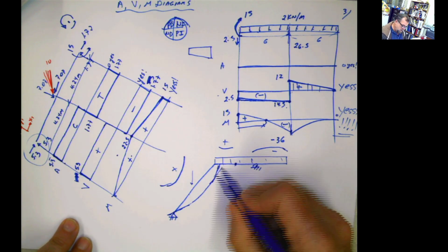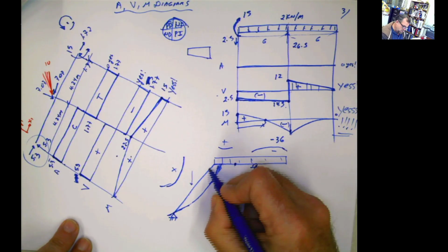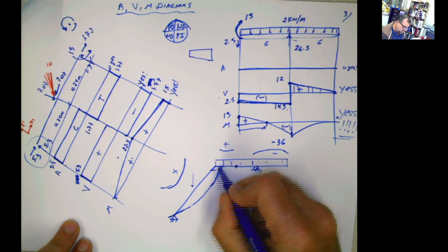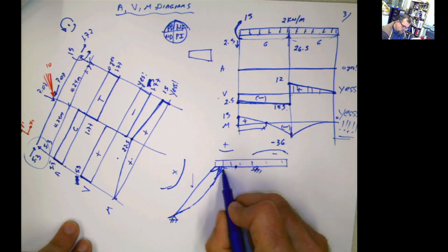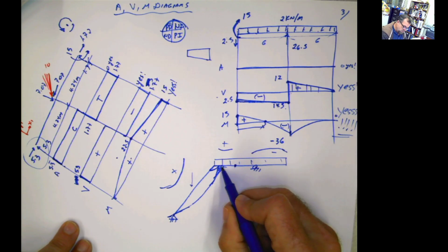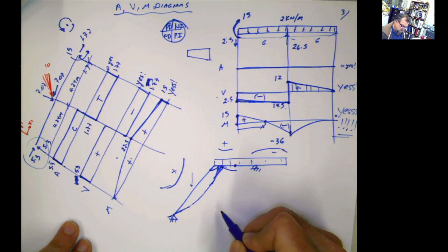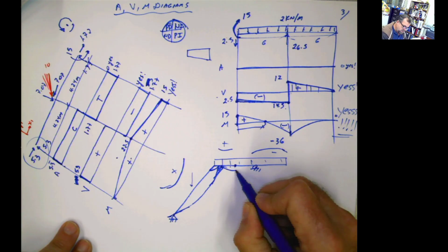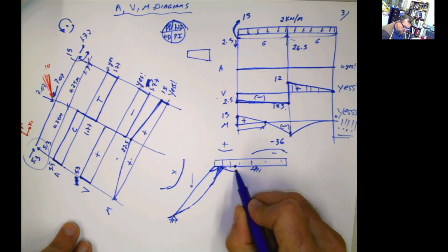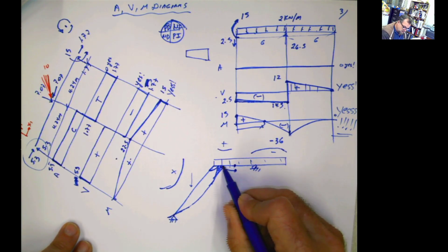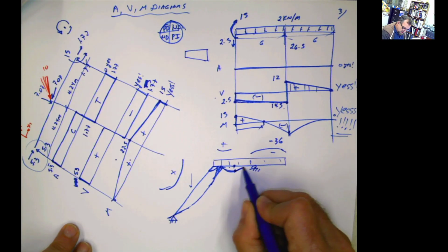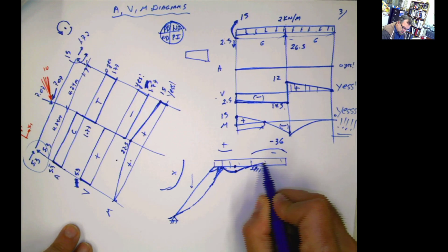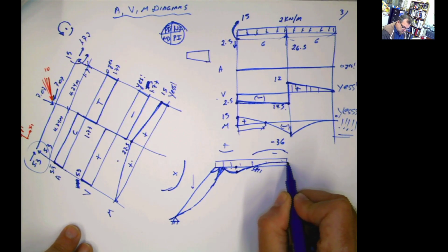But this is a moment connection, so that angle that I have over there has to be maintained somehow here. And this is positive up to this point, like there. And then after that, everything becomes negative. So this is the inflection point. This is going to be like that, positive, and now here it's going to start switching to negative, like this. And it's going to end somewhere like that.